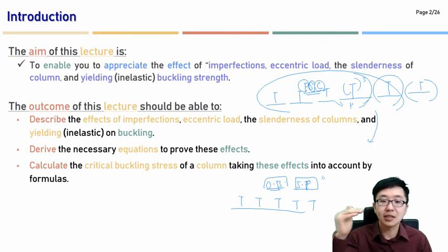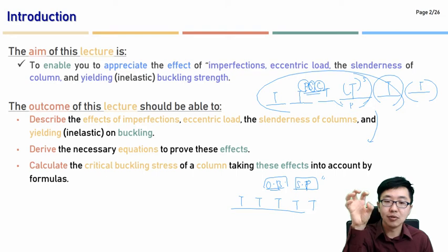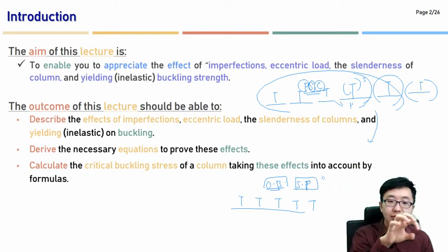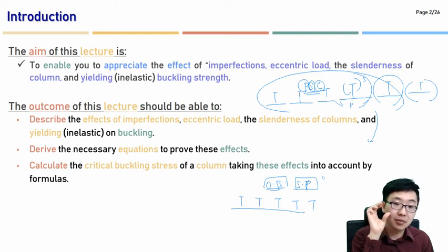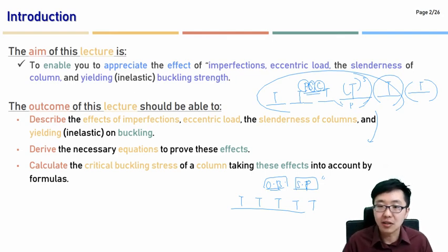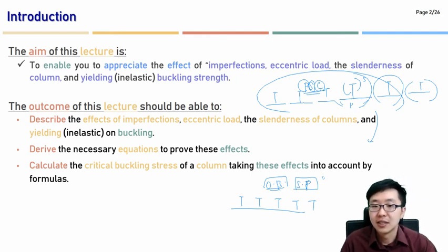Once we complete the global strength analysis, we will route that information to our local strength analysis. That information, the applied force or stress, will be used to judge whether our local buckling capacity is good enough or not. So here we will decide whether the column will be safe or not.